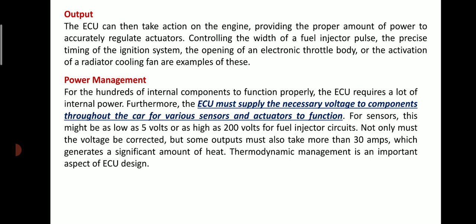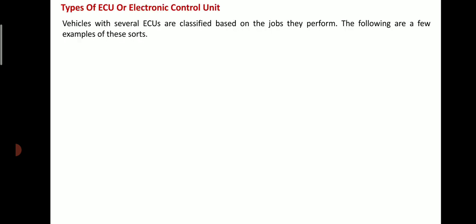Fourth is power management. For the hundreds of internal components to function properly, the ECU requires a lot of internal power. Furthermore, the ECU must supply the necessary voltage to components throughout the car for various sensors and actuators to function. For sensors, this might be as low as 5 volts or as high as 200 volts for fuel injector circuits. Not only must the voltage be corrected, but the output must also take more than 30 amperes, which generates a significant amount of heat. Thermodynamic management is also an important aspect of ECU design.